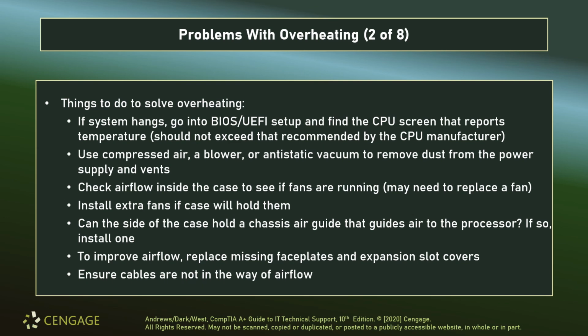Check airflow inside of your case to see if your fans are running. Install extras if you can. Chassis air guides are not bad ideas. Those will guide air directly to your processor, being that that's usually the hottest component. Sometimes, of course, high-end graphic cards and power supplies can go a little hotter. It just depends, but CAGs are always helpful. I think Intel and AMD both recommend them.